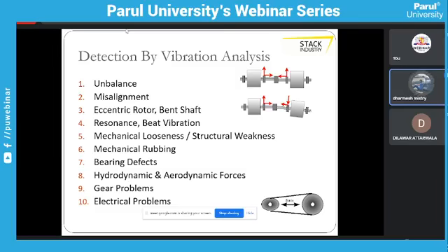And in the third bottom image I have shown two pulleys with a belt. For example, the belt is tight or the belt is loose. The pulley will go plus minus and it will create a vibration. This is called resonance vibration, which is continuous, but it will definitely damage something or the other. It will either damage a pulley, or a bearing, or anything further.